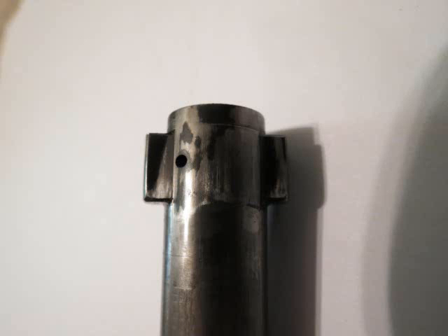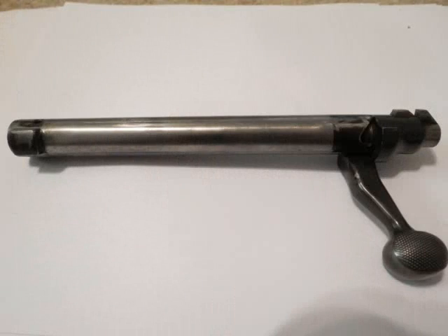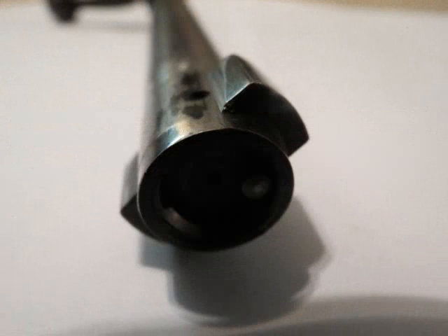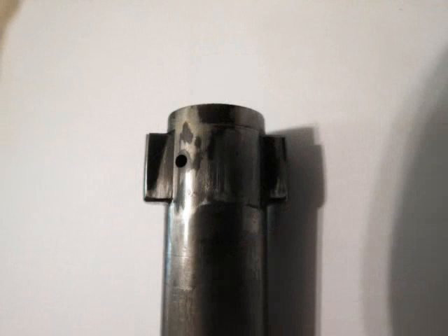So what you want, like I said before, is absolute consistency between all the different parts that could be moving. So, for example, you have two lugs on the back of this bolt here, right? Let's say the right side is more firmly mated up and the left side is a little loose. Well, if it's a little loose on one side and tighter on the other, then when the rifle starts vibrating, before the bullet exits the muzzle, you can have two surfaces pounding up against each other, and that can really introduce some strange anomalies in the vibratory pattern of the harmonics, and that can throw off your accuracy quite tremendously, actually, sometimes.